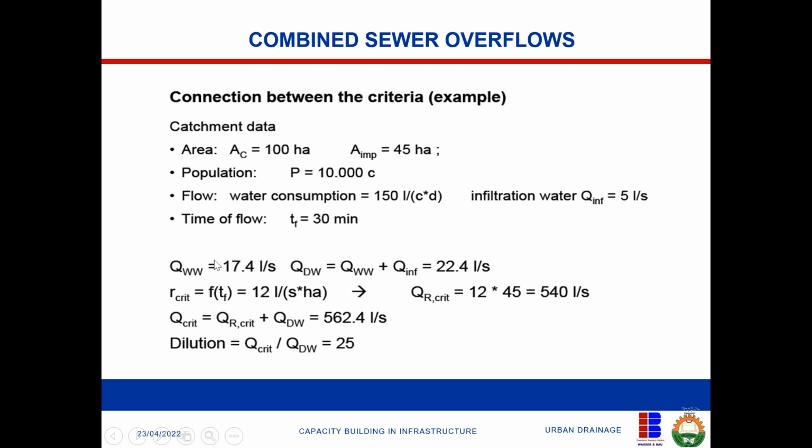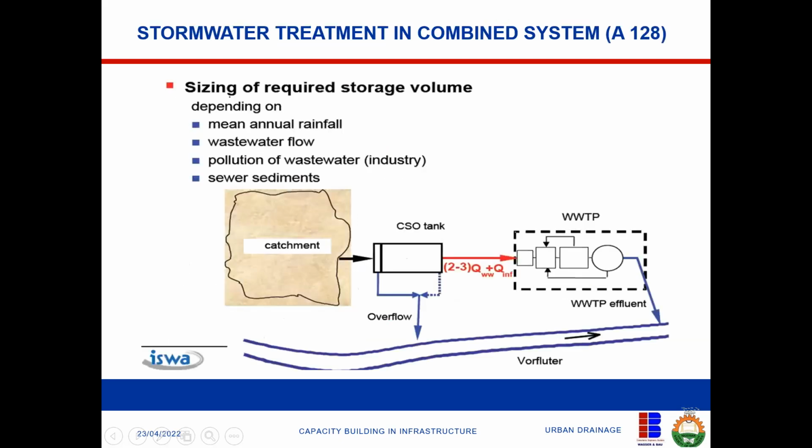For the total sewer flow, this is the wastewater flow. For the sewer, it is the wastewater flow plus the infiltration flow. This will confuse some of us for now. So here, you will see how to size based on another code.